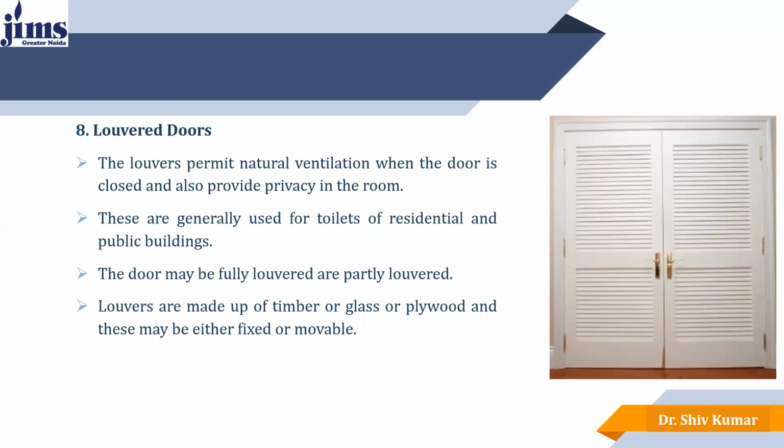The next is the louvered doors. The louvers permit natural ventilation when the door is closed and also provide privacy in the room. These louvered doors were provided in previous times, but nowadays these are avoided because they are comparatively less strong.